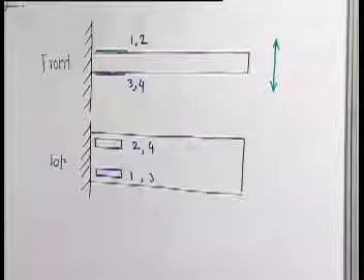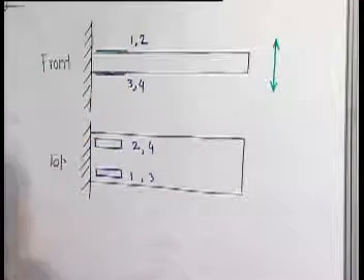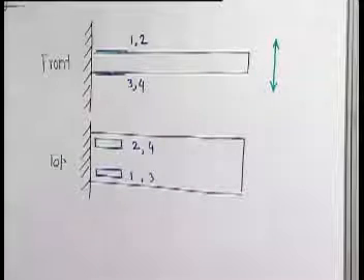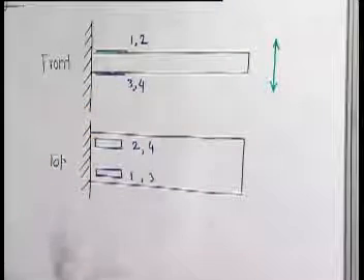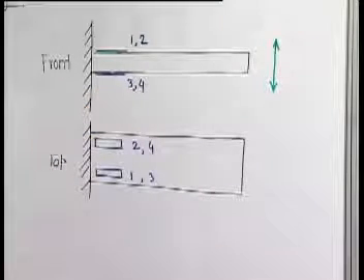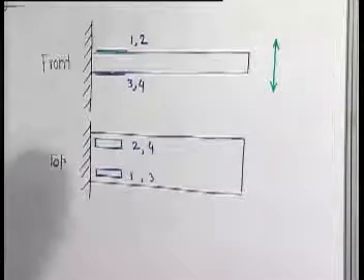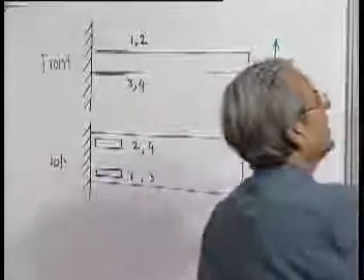During bending, 1 and 2 are undergoing tension, meaning resistance will increase. Similarly, on this side under compression, resistance will decrease. Now this is used in the form of a bridge and a voltage is generated in this manner.